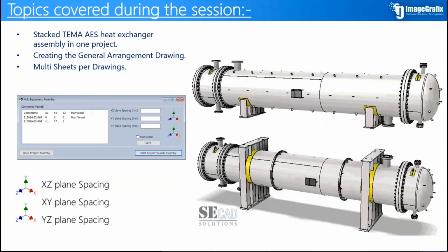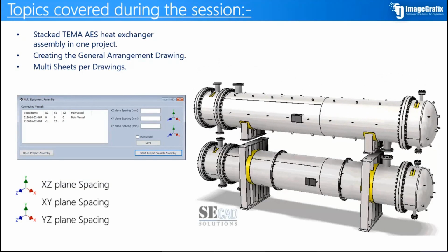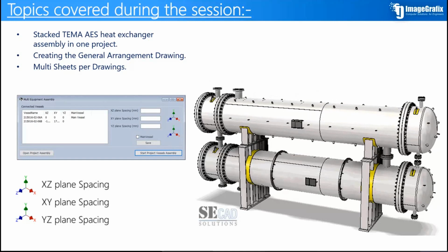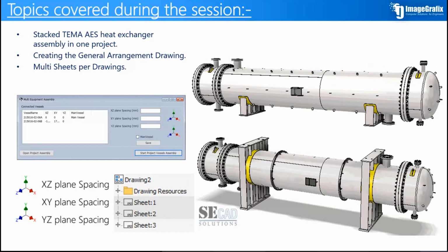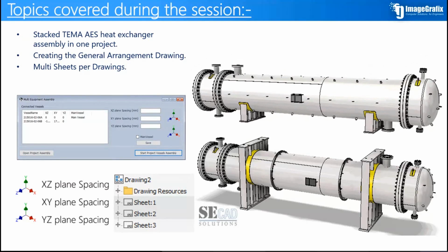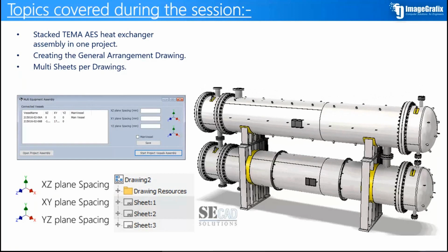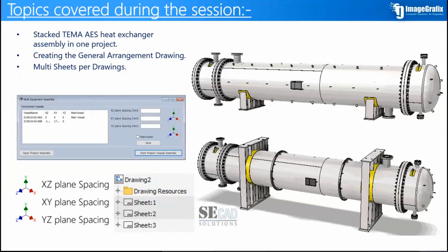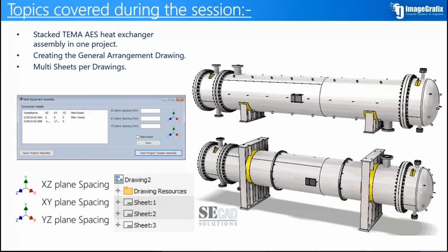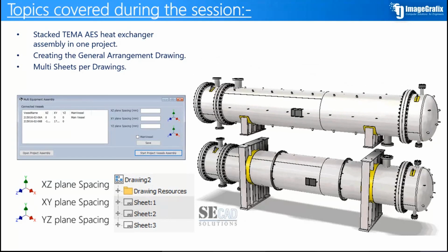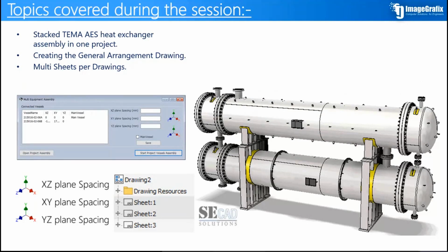In some cases with large equipment, you have a large bill of material. If you add all the information in one sheet in your drawing, like the views of the equipment, the nozzle table, bill of material, and design data, all of that in one sheet would be a lot of information in one drawing. If you would like to separate some information into different sheets, you have the ability to do that by using a tool for making separate sheets in your drawing.